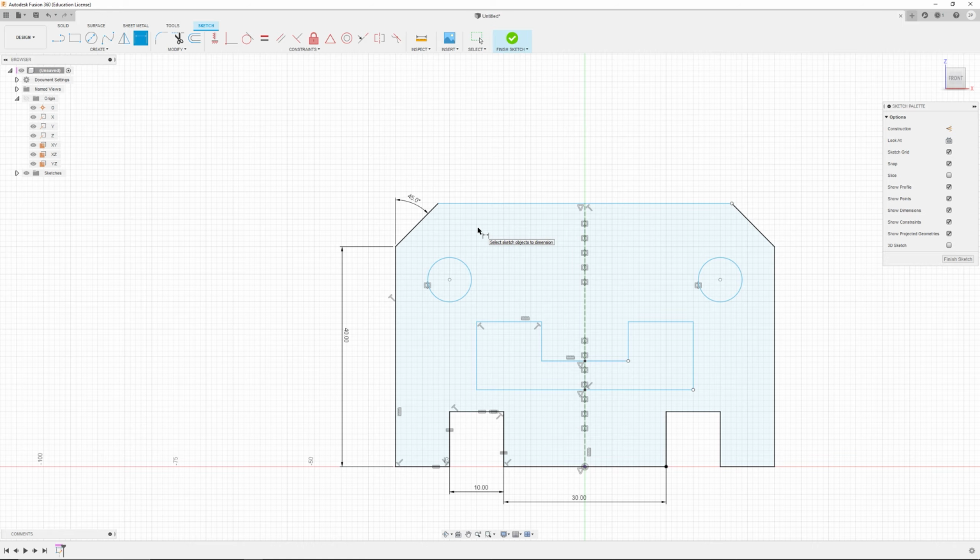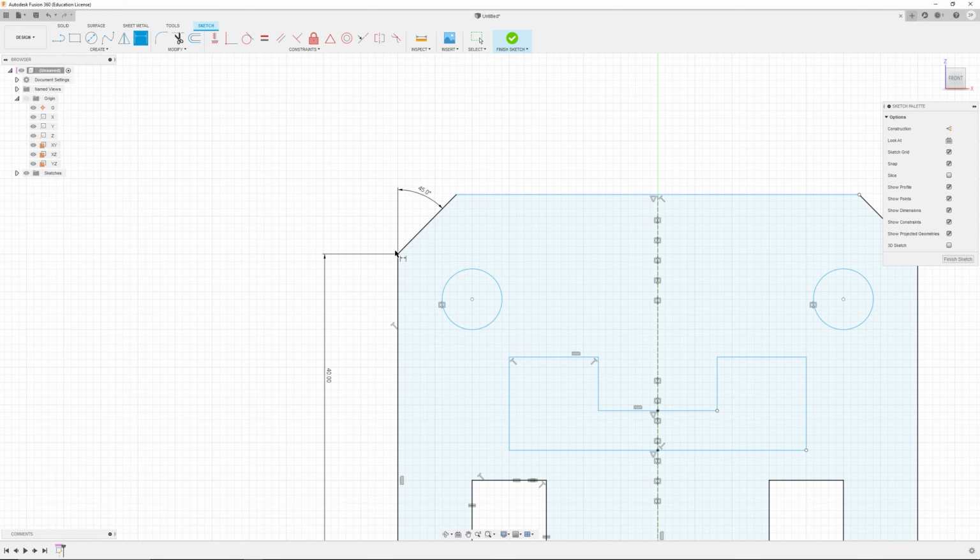And what does that tell us? Oh, one more thing. From here to here, and this time I selected points. You could also select the line and then drag out to the left. There's two different ways of measuring that one. So again, it's either point to point, drag, or select the entire line. And if I come out parallel to it, it will give me that parallel dimension. Or if I come out to the left, it'll give me that linear dimension. That value is going to equal 10.